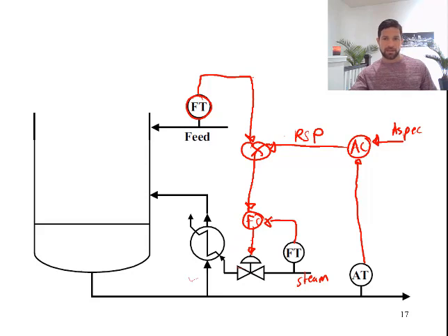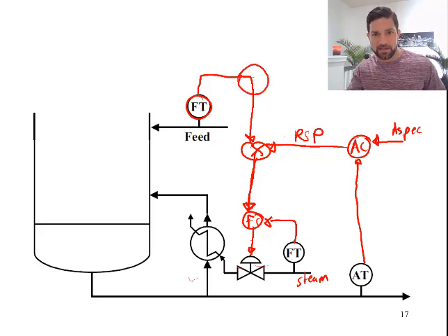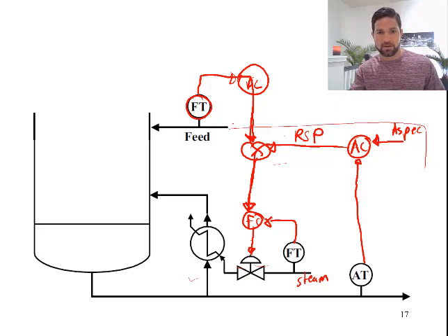but there's really only one place where it makes sense. Okay, so this primary control loop is setting the ratio between the measurement of the feed to the system. So the ratio calculation is going directly to the cascaded flow controller. Where we need to put the dynamic compensator is right before the ratio controller. If we put it after the ratio controller, the ratio is going to be calculated and the dynamic compensator is going to interfere with the primary feedback control loop. So this loop right here should be independent of the feed-forward stream.